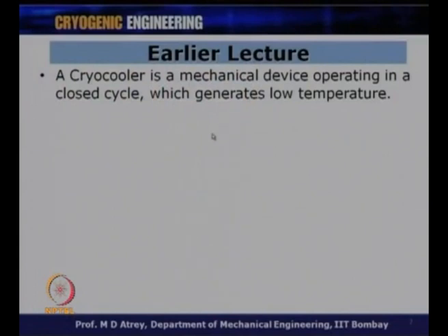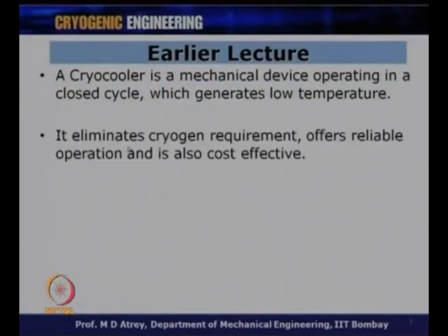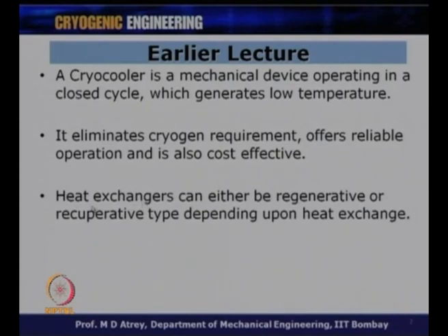A cryocooler is a mechanical device operating in a closed cycle manner which generates low temperature. And I compared this to a domestic refrigerator wherein you get low temperature in a closed cycle manner. What does it do? It basically eliminates cryogenic requirement, offers reliable operation, and it is cost effective. There are different heat exchangers, and these heat exchangers can either be regenerative type or of recuperative type depending on the type of heat exchange we want to have. And depending on this, we had classified the cryocoolers.